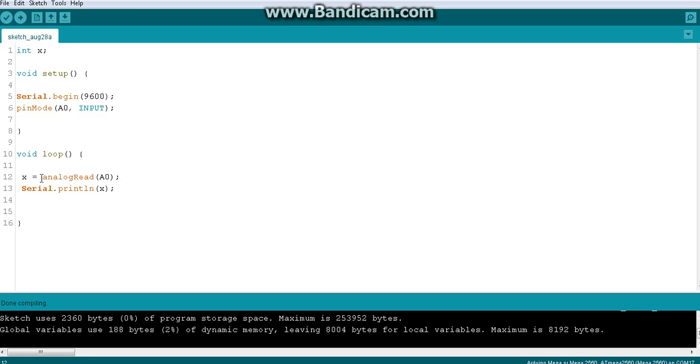Apart from that, you should also know that you are getting the real-world, real-time value because the void loop is repetitively running, right? So if I suddenly open my serial monitor and see the x value, I am getting the current value. After 30 minutes, if I come and check the serial monitor, I will get the latest value at that time, because the void loop is repetitively running forever, right? So every moment this x value is being assigned by the analog read. So that's totally cool, right?